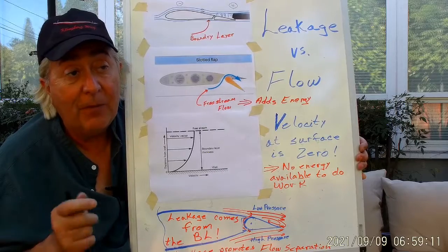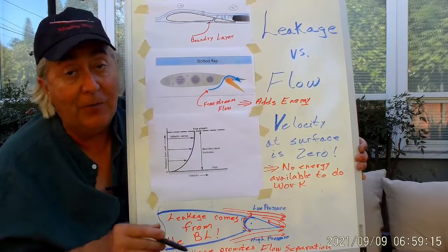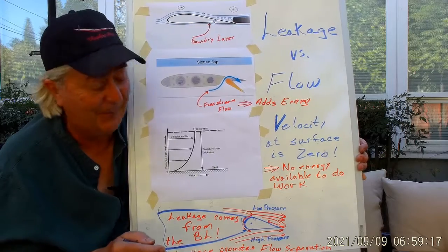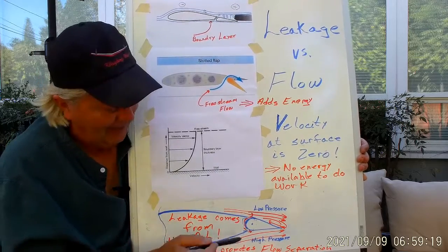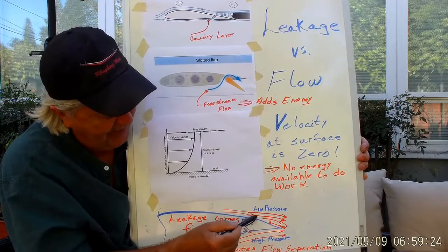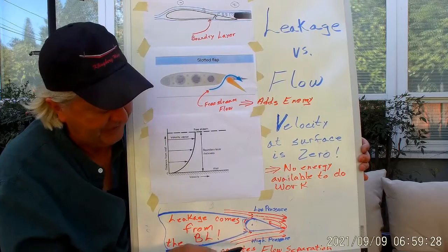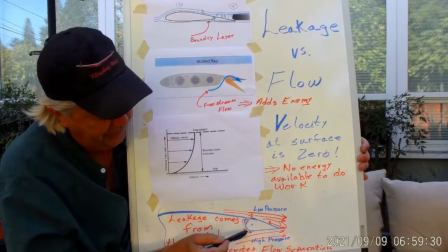A lot of people that were writing in were, and as aerodynamicists, we always talk about flow. Nobody ever says leakage. It's not a technical term that we use, but it's really what's happening, is that the air is leaking through the gap and going out the top and disturbing the flow here and rendering the control surface ineffective if too much of this gets through.